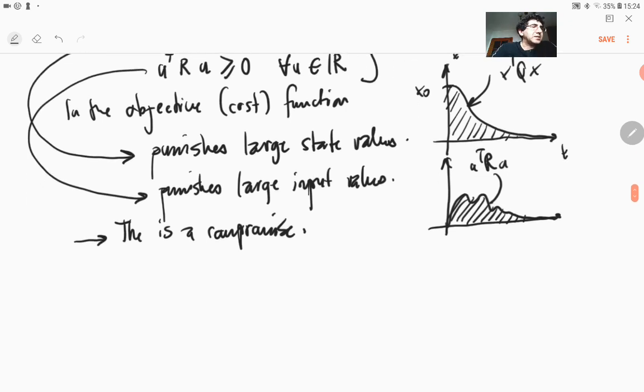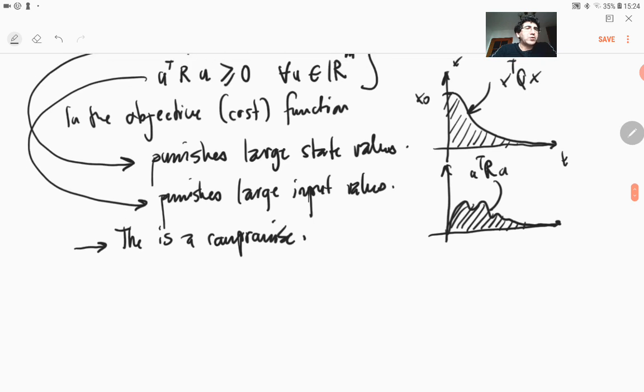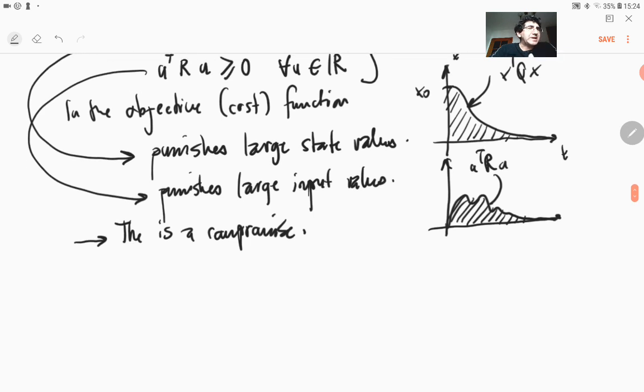You cannot go to the limits of the motors, because that's going to create nonlinearities, and you will not be able to generate the necessary torques. So by using a linear quadratic regulator, you can generate a compromising solution where you do your best to drive the states to 0 while also maintaining a certain cap on the input.